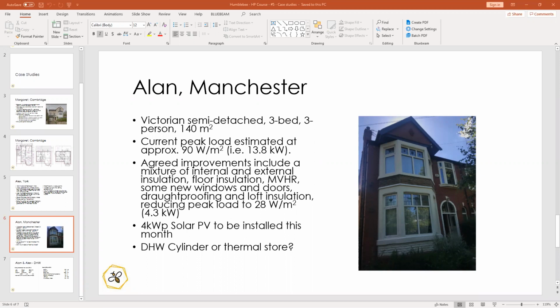No worries. The other plus for a thermal store is not having to do the Legionella control, because obviously you're not using that water directly, and you're getting instantaneous hot water out of your taps. That's the only other thing. So there might be a calculation to do to see what the trade-off is in terms of energy, but it sounds to me like a lot of people are making hot water cylinders work more efficiently. So we can discuss it as part of the next stage.